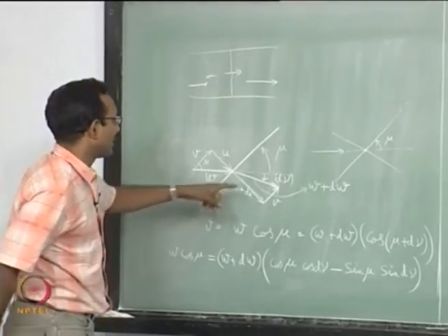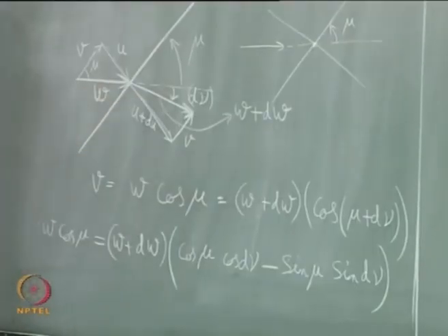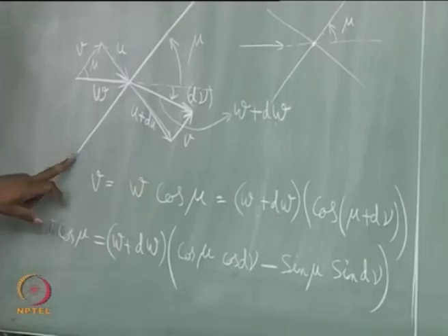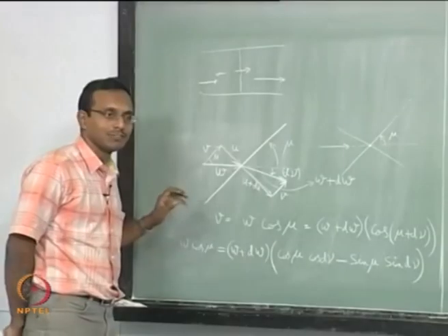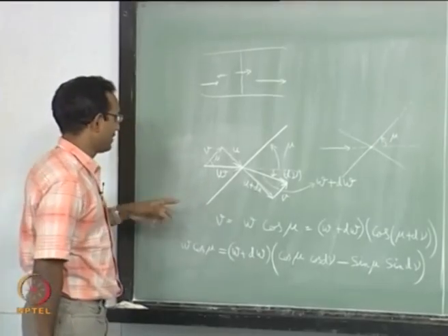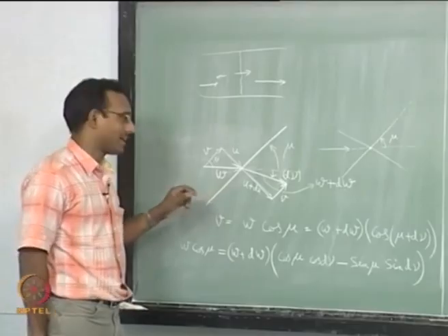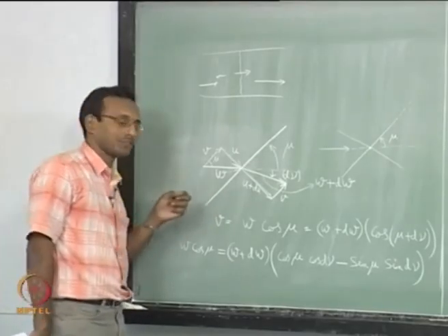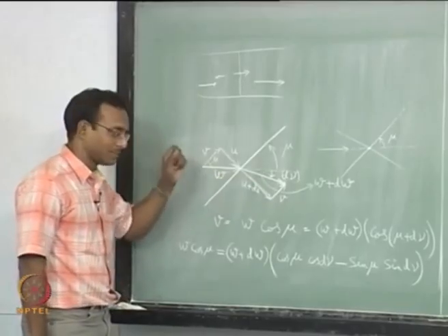I am going to say that this d nu is a very small deflection. Why? I have considered only one wave, which can affect only extremely small quantities, right. That is what we said in the last two classes. One single expansion wave, which is almost isentropic, can affect only a very small amount. So, the change cannot be very big, it has to be an extremely small value.